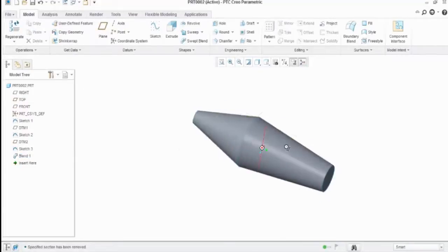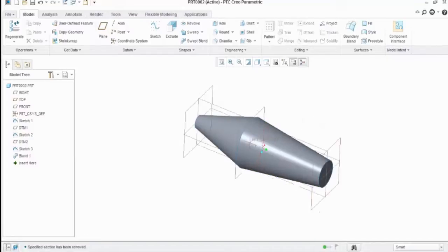Any doubts here? Yes. So this is the feature which is called blend feature. Blending means joining of multiple objects, multiple circles, rectangles, multiple profiles. This is the option. And here is the next operation we have, which is called sweep. Sweep is basically working like this feature, but the whole difference is path. We are sweeping one profile along some path, that is called sweep command, right?